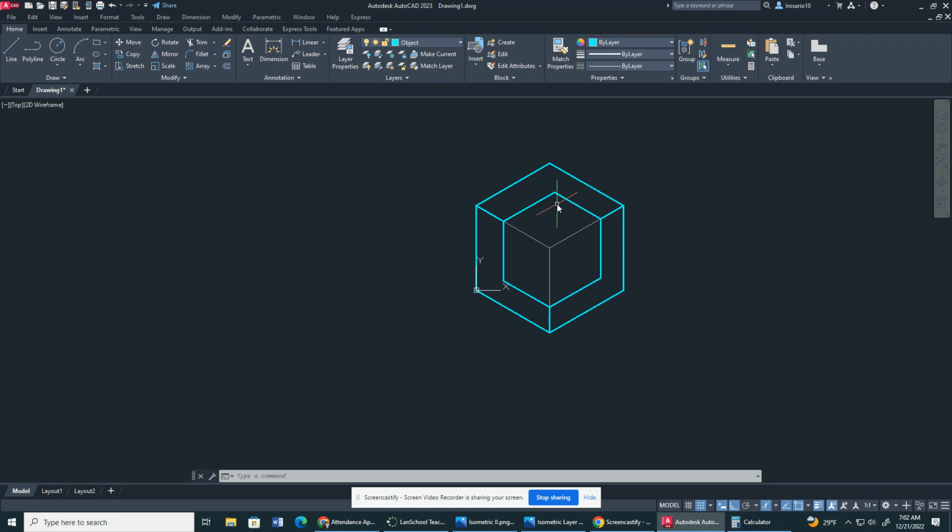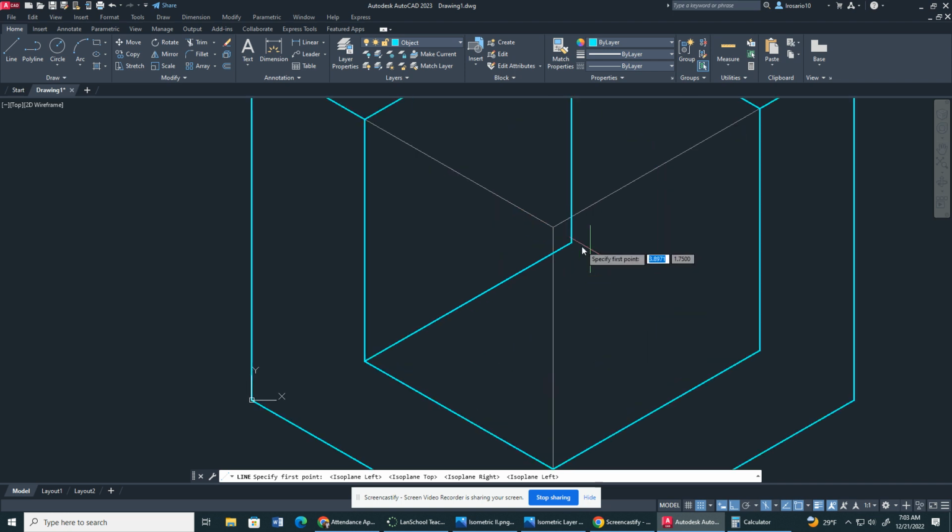We go right here, straight down. That's going to be 2.8. Connect it here. I'm going to press F5 for this one. Let's zoom in so we get that endpoint. I'm going to turn off my snap grid. I got this endpoint right here, and we connect it.